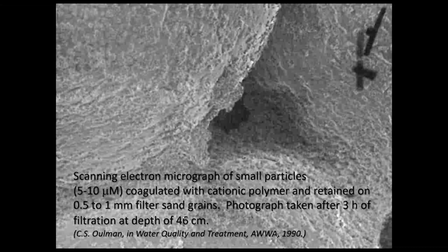So that also just shows you again, like we were discussing, you don't want to apply that sweep block to the top of the filter, because then you're not going to be able to take advantage of all of the surface area which these turbidity can adhere to. If you apply that sweep block, it's all just going to blind off the top of the filter and you're not going to be able to take advantage of your filter depth.